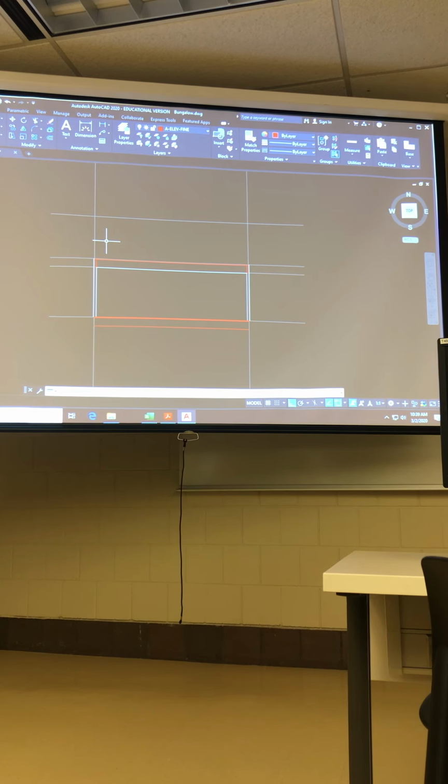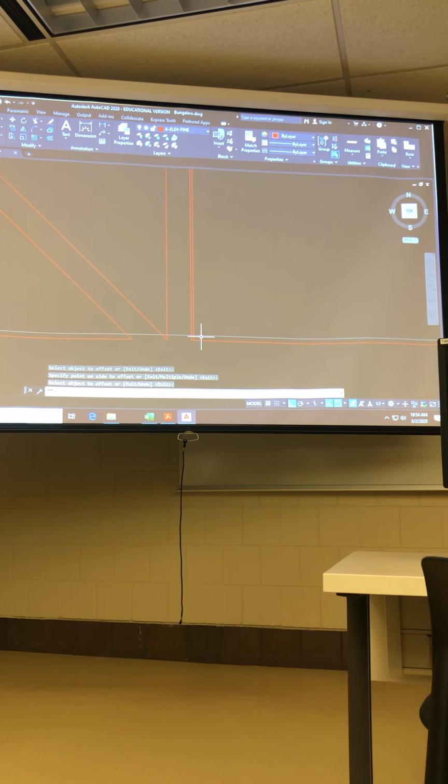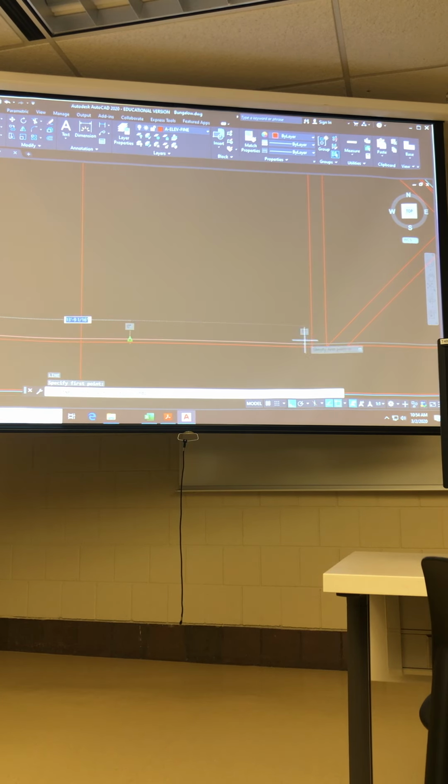And the next thing I can do is offset from my ceiling 5/8 of an inch. Offset for the walls, 1/2 inch. Before I do that, you know what I'm going to do? I'm going to go ahead and draw my floor sheathing. Get that in here. So that's from that point on my datum elevation to that point.